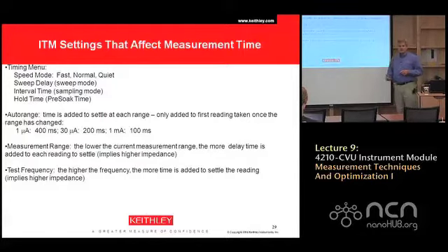What came up earlier was the question about auto range. Now, when we auto range an AC impedance meter, what we're changing is the current measurement range, just like a current measurement range on a DC meter. And so what we have to do is resettle that current range. Now, in the case of an AC impedance meter, we also have to settle the auto balance bridge, which adds some extra settling time. So what we have added for the first reading only after a range change are these default times. And these are very significant times.